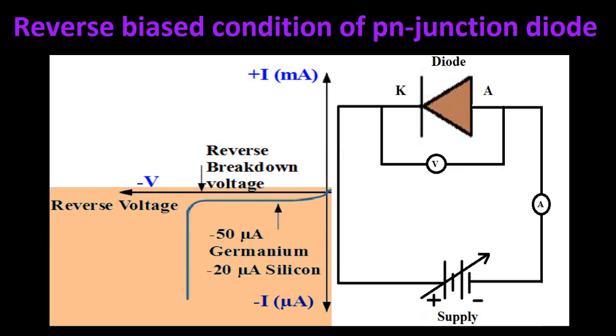If the reverse voltage is increased continuously, breakdown occurs at junction, causing sudden fall of resistance, which results in sharp rise in reverse saturation current. The minimum reverse voltage at which PN junction breaks down with sudden rise in reverse current is known as breakdown or avalanche region.